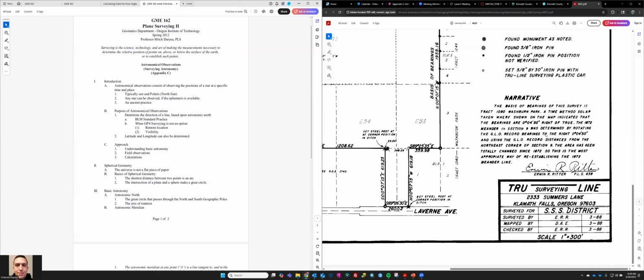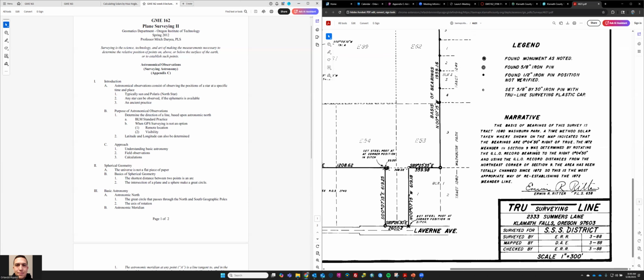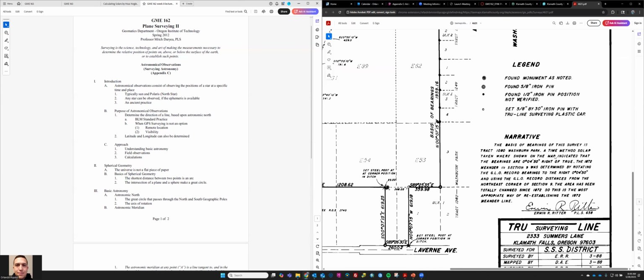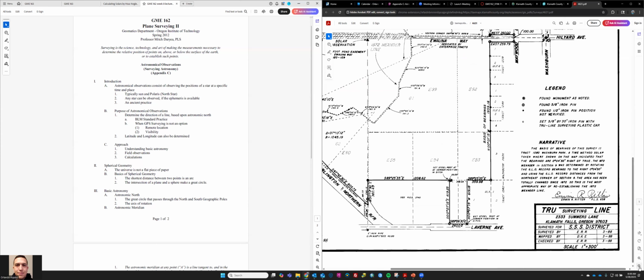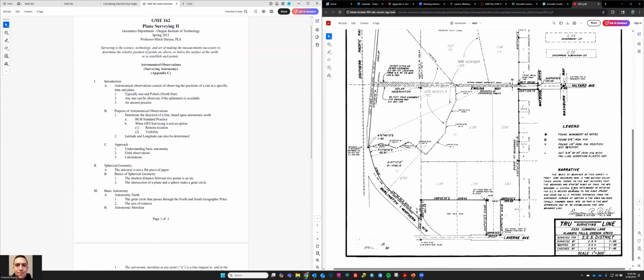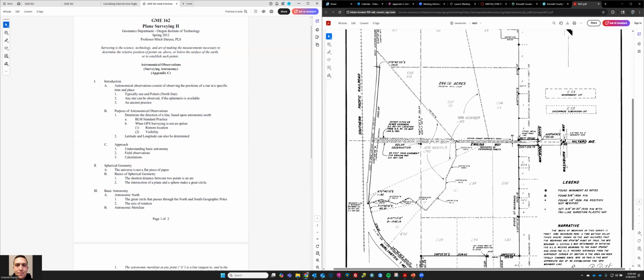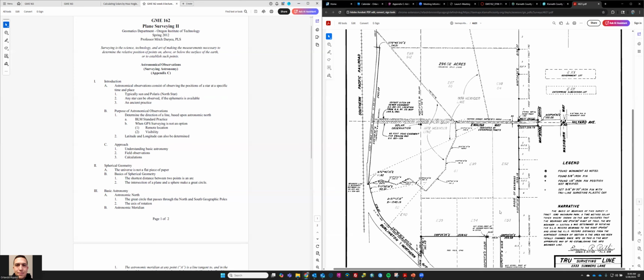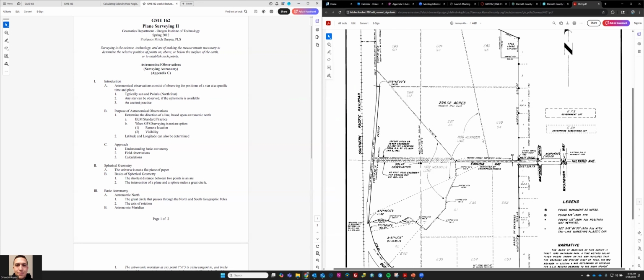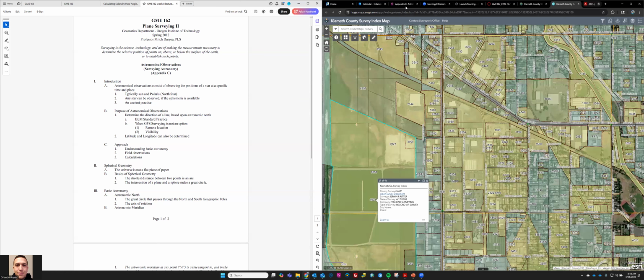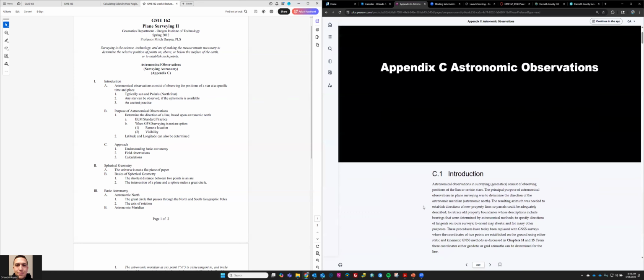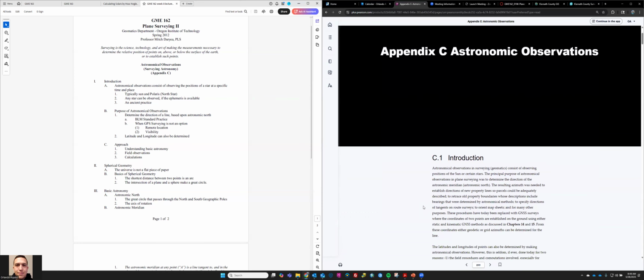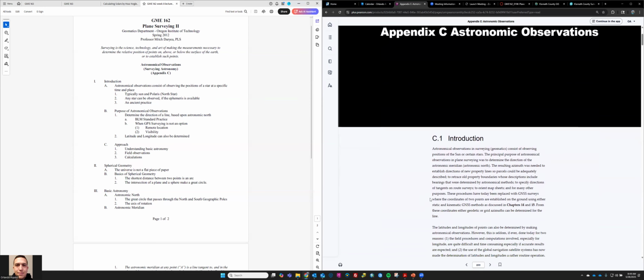1872 meander. So that's again another time. So again, this is done by our surveyor Erwin Ritter. Did many around the basin. So this was a perfect example of how to establish a basis of bearing via time solar, and this method has been outdated as we will go through our book here, but that was one of the first ways of establishing a basis of bearing for boundary work.